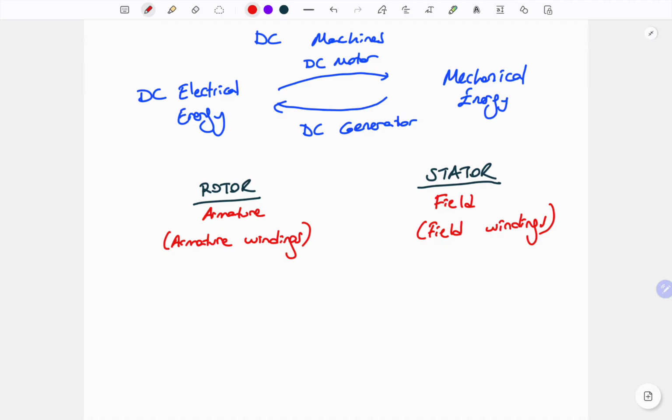The reason for this is their construction. In the industrial case, they have bars to transfer the voltage from the terminal to the rotor part, or from the rotor to the terminal part. They have a commutator structure and the bars, so they need extra regular maintenance and extra cost because of this.